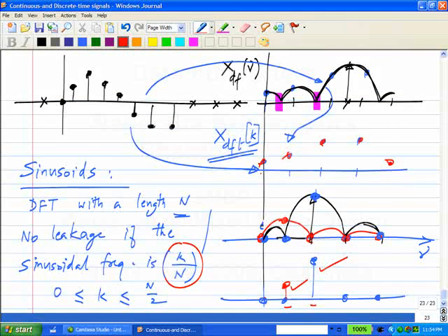So now this is the point I will be coming to next. There are cases where you can choose the sinusoidal frequency. For instance, you are testing an A to D, and what frequency you test it with is up to you. If it is a little bit here or there, it's okay. So you will acquire the data and decide to take n-point FFT, where n can be some large number, 2 to the 16 or something. Then you choose the frequency to be some k by n times the sampling frequency.